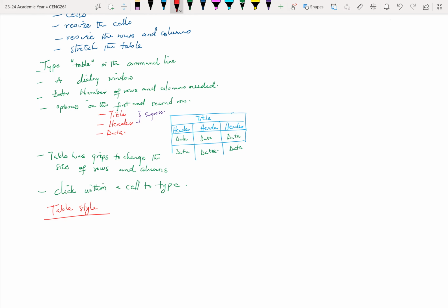For that key reason, you'll realize that most of the things we have been talking about, you would always end up with a dimension style, a table style, a multi-leader style, a text style, so that these can be used to create the templates you need, so that you can reuse them in the engineering or architectural office space.